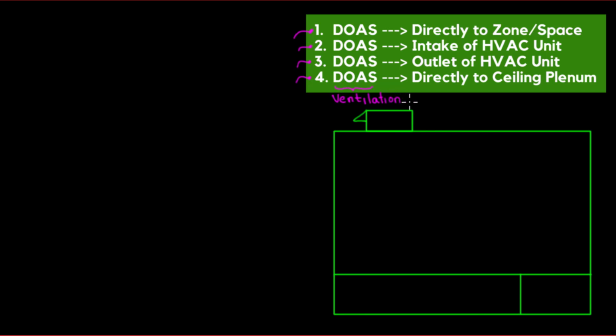In other words, conditioning. So for conditioning, we're talking about the local HVAC unit, local equipment, right? Okay, so usually this local HVAC unit, what they do is they recirculate air. So recirculation. Okay, in other words, you have supply and return, but you need to find a way to tap ventilation, like the outside air.